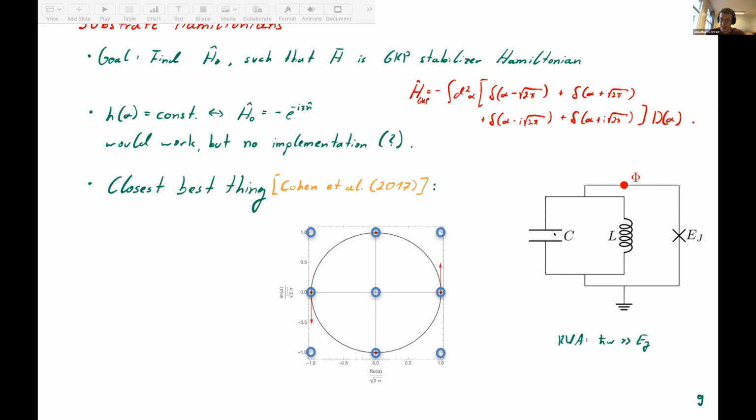So the Josephson junction has a Hamiltonian characteristic function, which is given by 2 dots up here and down here on the imaginary line, where the radius or the distance of these deltas to the center point at phase space is given by the impedance of this LC circuit here. So if I go into the rotating frame of the circuit, what's going to start to happen is that these dots are going to start to rotate in a circle.